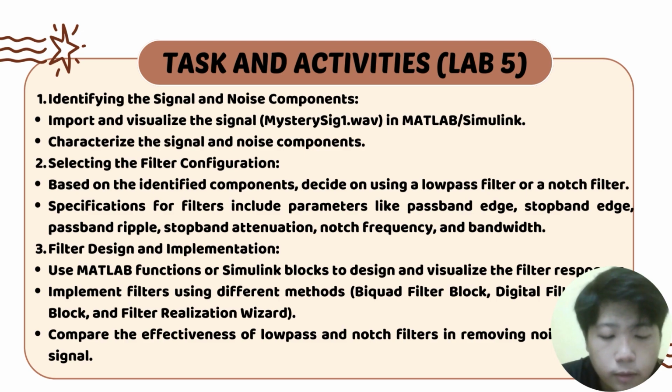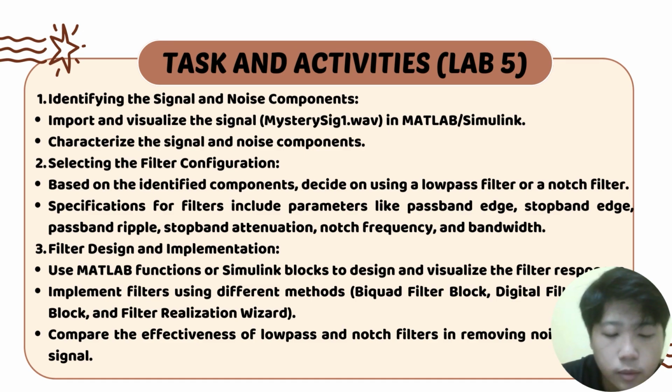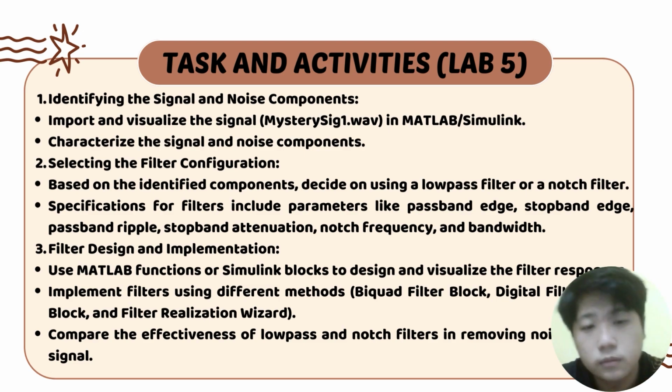Specifications for the filter include parameters like passband edge, passband ripple, stopband attenuation, notch frequency, and bandwidth. For the filter design implementation, we use MATLAB functions or Simulink blocks to design and visualize the filter responses. We implement the filter using different methods, such as Butterworth filter blocks, digital filter design blocks, and the filter realization wizard. We compare the effectiveness of a low pass and a notch filter in removing noise from the signal.